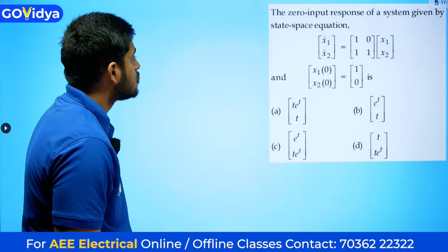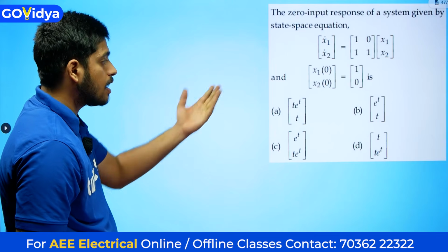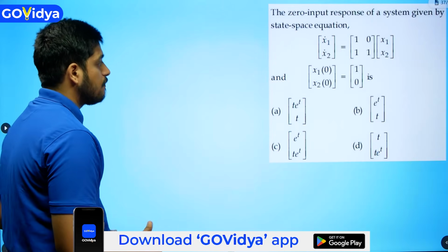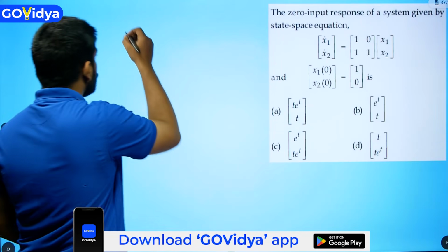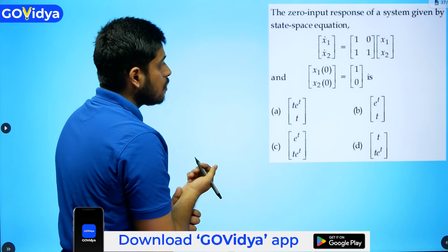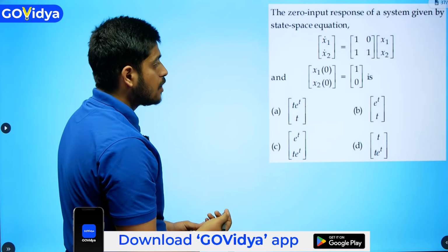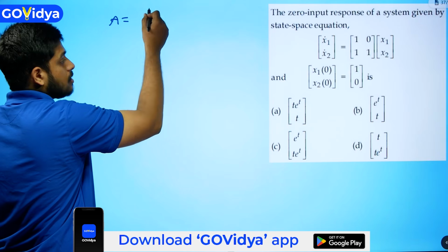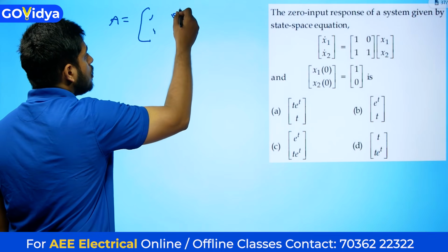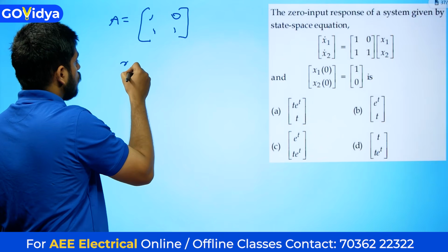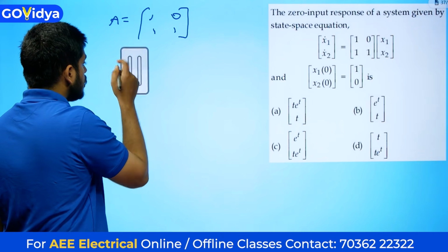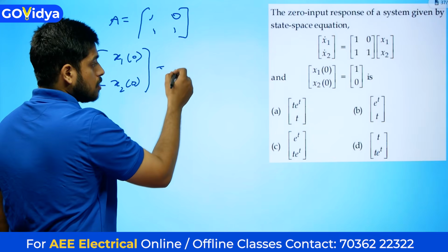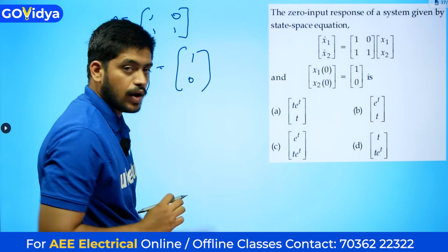Okay, next question. The zero input response of the system is given by some state equations in matrix form. So we need to find the zero input response. Let us first resolve what those equations are. x1 dot and x2 dot are given as the matrix 1 0 1 1 into x1 of t and x2 of t. So matrix A is 1 0 1 1, and the initial condition x1 of 0 and x2 of 0 is 1 and 0.